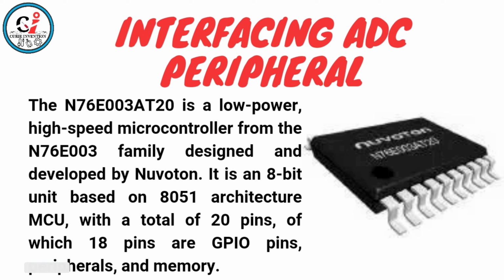Interfacing ADC peripheral. The N76E003 is a low-power, high-speed microcontroller from the N76E003 family designed and developed by Nuvoton. It is an 8-bit MCU based on 8051 architecture with a total of 20 pins, of which 18 pins are GPIO pins, peripherals, and memory.